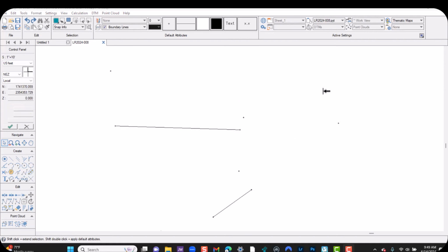The last area is how do I measure these lines or measure between points on lines? Well, first of all, if I just hover over a particular line, or I can highlight the line, if you look over on the left, you'll see that I have a length of 47.616 US feet. So any object like that, I can actually measure that way. This one is 17.964 feet.